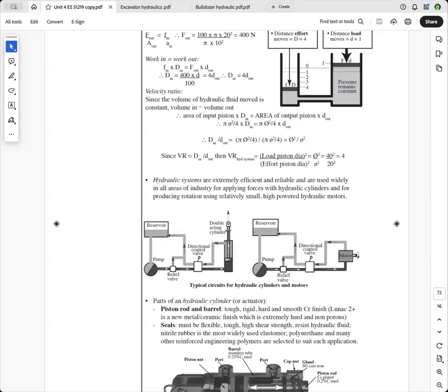And when you want the hydraulic ram to go in, you change the lever and the fluid changes and goes in here and drives the ram down. This is a hydraulic motor. This is the one that drives those agitators on the concrete truck. So you've got everything set up the same, and you've got a really efficient method of driving a pump.